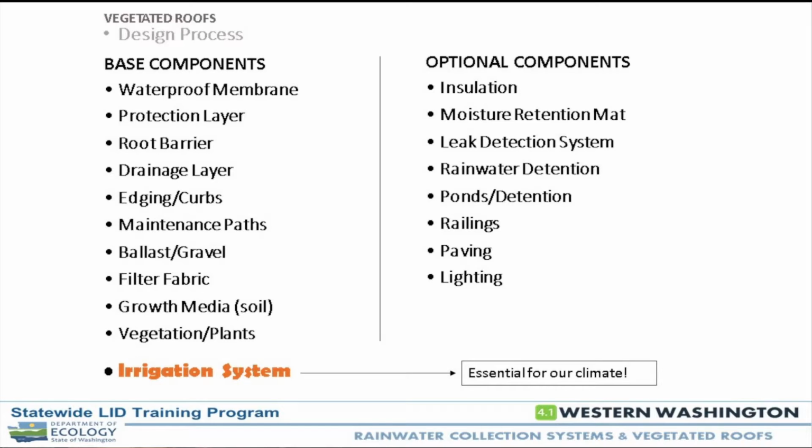Basically, there's a very small set of materials that need to go into it. There's a lot of products that people like to sell you. These are actually really simple systems. So you have a waterproof membrane, and the key part of roofing and implementation of a green roof is to protect the waterproofing at all costs. So you'll see redundancy, and you'll see specific products, but also processes that are really aimed towards doing that.